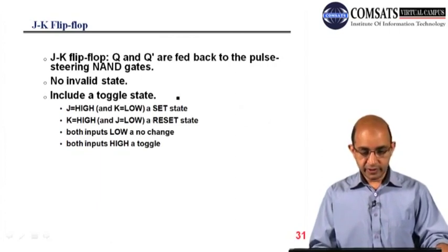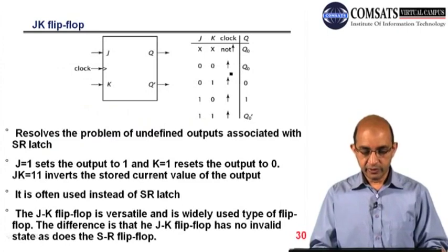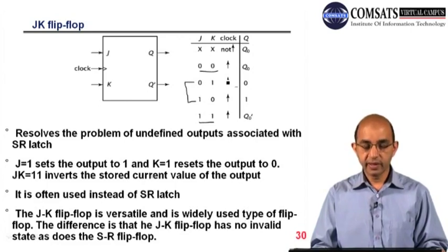So this is the JK flip-flop. You can see we have the table. Here you can see Q follows J on the active clock. And these 2 are the exceptions. Here 0 0 no change, and 1 1 toggle, and for the rest of the 2 combinations, Q follows J. This is the rising edge, so you can see Q follows J, Q follows J, and this is no change. And here we have the complement of this clock, or you can say we have an arrow that is pointing down.